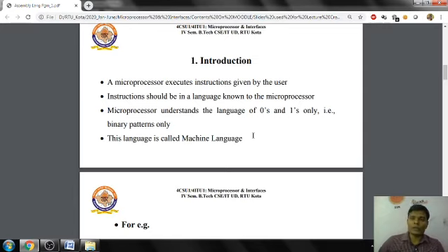One by one, the microprocessor has to start with a location, then jump to another location until it finishes all of your instructions, and then finally it produces its result. And results get stored either in the accumulator, which is one of the 8-bit registers of your 8085 microprocessor, or you can redirect the result to some output port too, or any other peripheral device which is acting as an output device for your microprocessor.